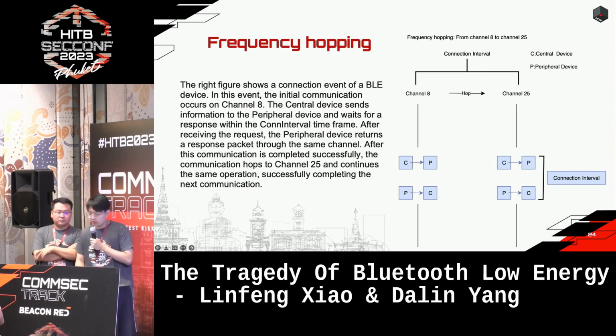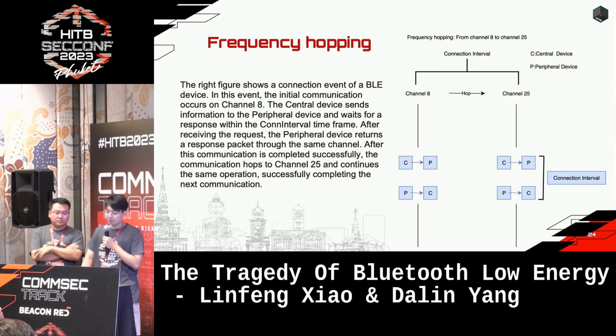And the right figure shows a connection event of a BLE device. In this event, the initial communication occurs on channel 8, and the central device sends information to the peripheral device and waits for a response within the conventional connection interval time frame. After receiving the request, the peripheral device returns a response package through the same channel. After the communication is completed successfully, the communication hops to channel 25 and continues the same operations, successfully completing the next communication.